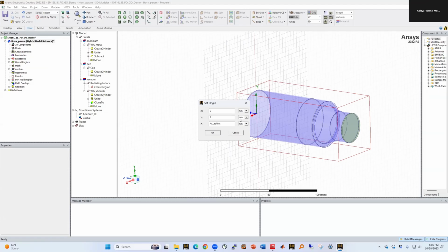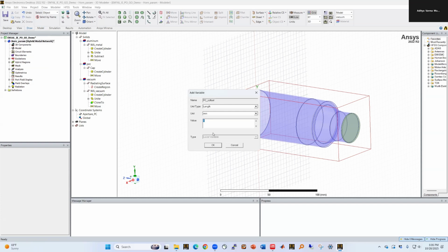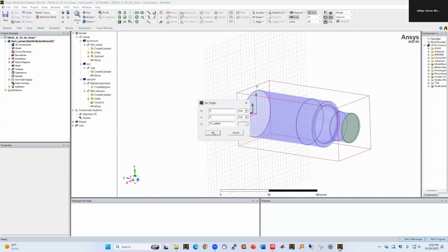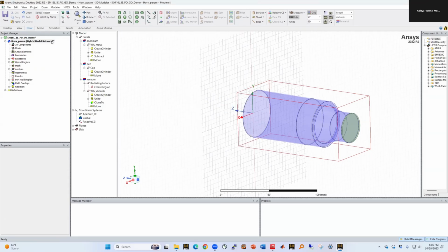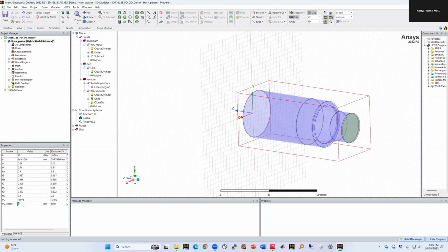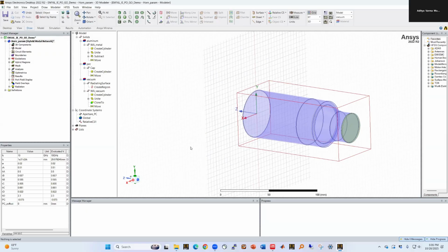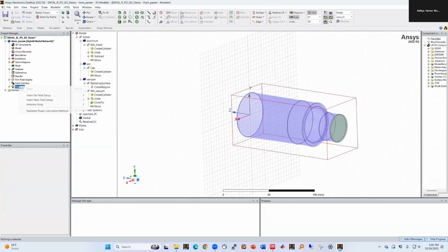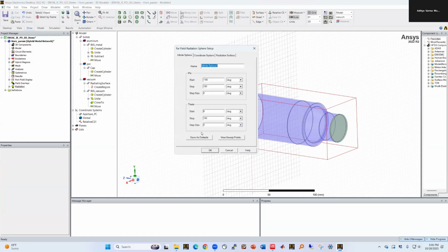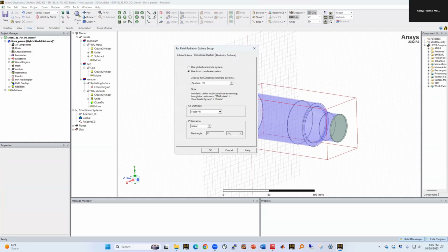All right, so if you don't get this option, you should hit F4 and it'll take you to this option. You can go to my website and look at different HFSS hotkeys if you haven't seen that before. So I'll set this to some value, say 5 millimeters. Now you can see that this moves as I change this value, right?